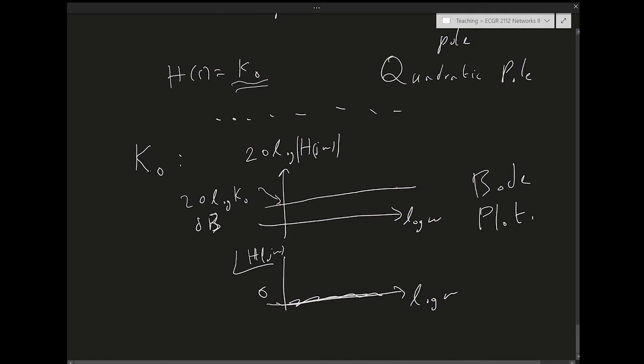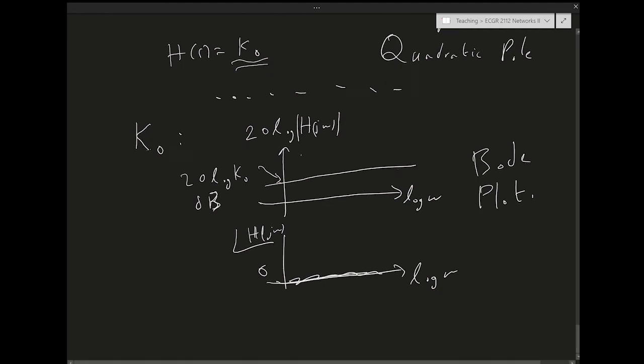And if we have a complicated Bode plot and then we have a constant, the constant is just a straight line, and we said in Bode plots when we take everything together, we just add everything with each other. So really, once we have a complicated Bode plot, the constant is just a matter of shifting that Bode plot up or down by that amount. That's what it amounts to at the end. Right? So that's the constant.